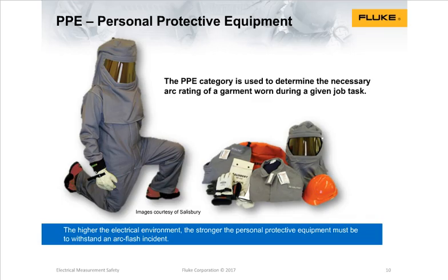PPE. There's some fine manufacturers of PPE. Wear the PPE. One thing that we noted when we talk to a lot of electricians is that there's an opportunity to grow complacent. The PPE is fantastic, and it's the right rating of PPE. But many people can grow complacent with making measurements on active panels if they haven't had an incident. And it's that complacency that says, it won't happen to me. I don't need to wear my electrical measurement safety gloves or eye protection or hearing protection, or I'll wear short sleeves without the flame resistant long sleeve clothing. And that's when incidents could likely occur.